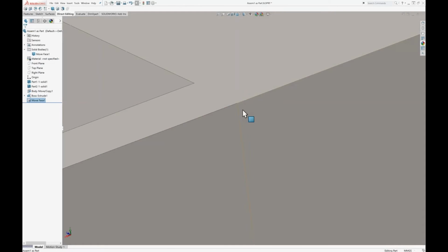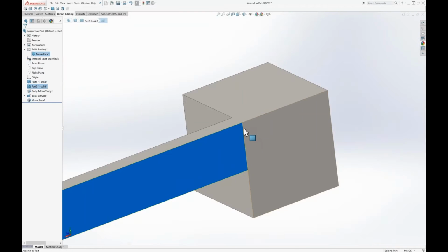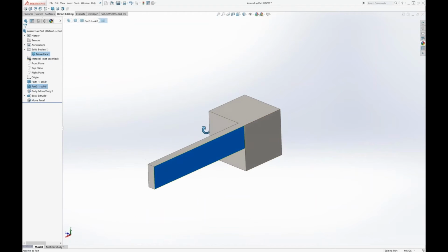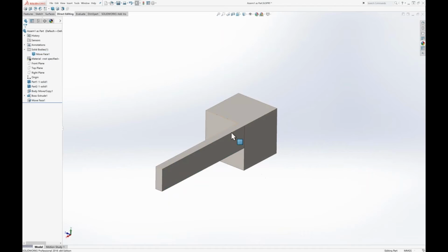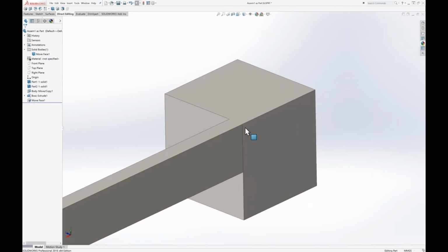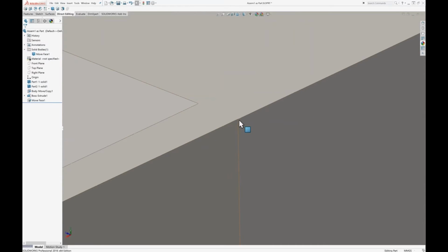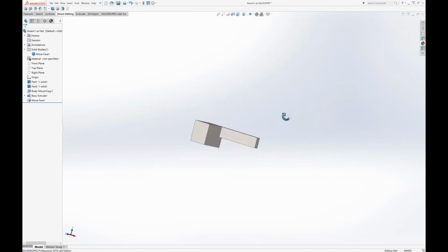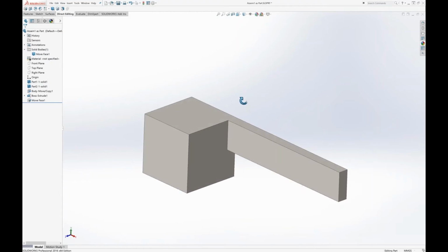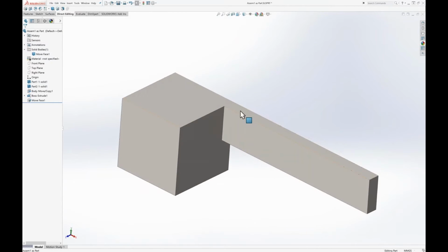So now when we look at this joint, there's still two faces because the angle still exists, and that might be important. But we've maintained all the important things. So we've maintained the thickness through here hasn't changed, the angle hasn't changed, but we've just removed the geometry that may be problematic. So that's the idea.